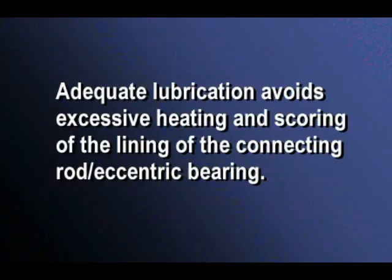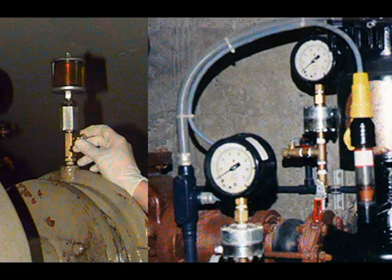It is important that the connecting rod eccentric bearing receives adequate lubrication to avoid excessive heating and scoring of the lining. Typically, a sight feed oiler is involved. This type of oiler requires manual opening when the pump is started and manual closing when the pump is shut down. A fully automatic ball-type oiler is becoming popular. This type of oiler automatically lubricates the connecting rod bearing without manually starting or stopping. The oiler is functional as long as the operating speed is above 44 strokes per minute.